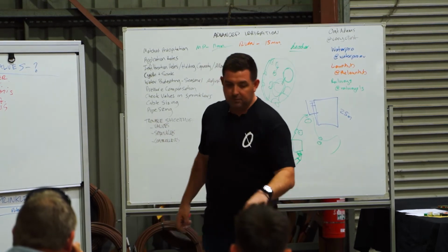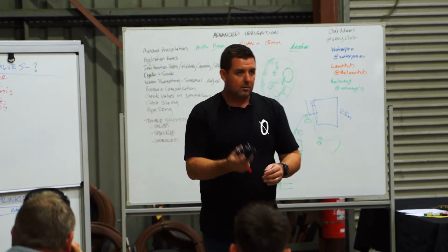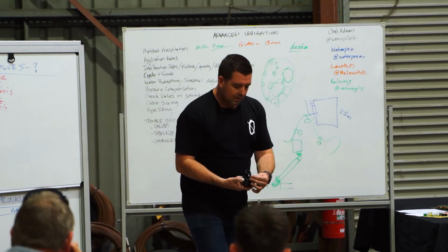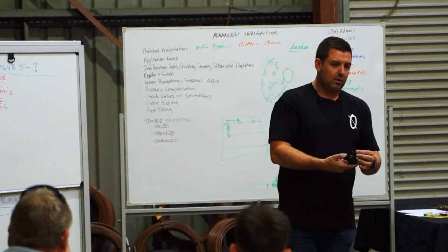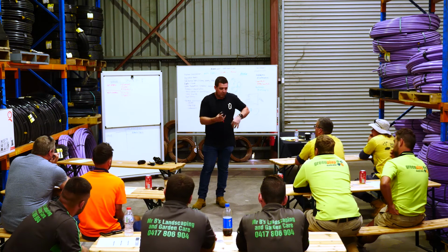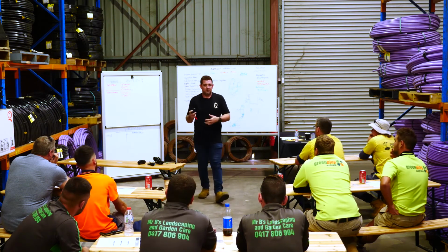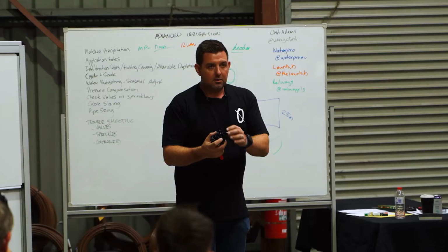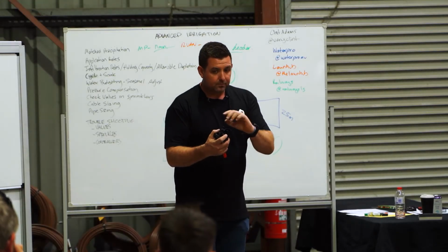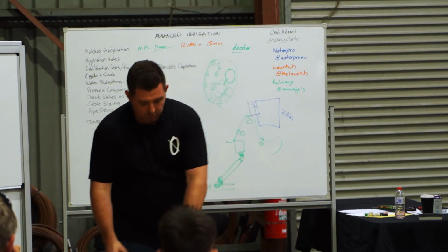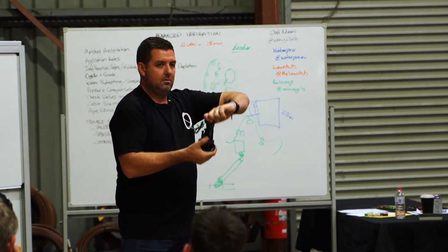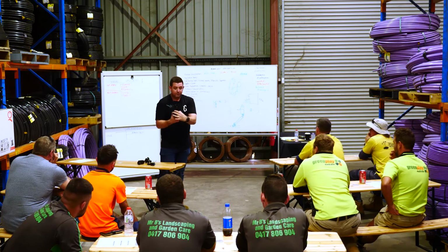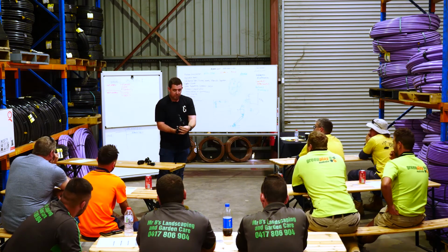There's another part of this valve called a bleed screw. Most of the solenoid valves that you work with will have a bleed screw. It's that screw there. If you unscrew that about a quarter to a half turn, the valve will turn on. The whole principle of a valve is the pressure changes from a release at the top and the valve opens. Electronically, that's lifting a pin. Manually, by turning a coil like a quarter turn, you simulate that pin lifting electronically, it opens. Further manually, you open this bleed screw, it does the same thing.